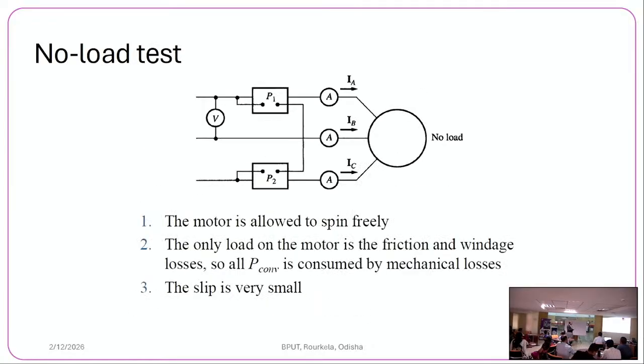After that, whether you have to calculate with AC resistance, you have to multiply by 1.6. AC resistance, okay, that's what I have not told. In DC, whatever resistance you get, in AC the 50 Hz resistance will be more. Why will it be more? Who can tell? Because of the skin effect, the resistance will be more.